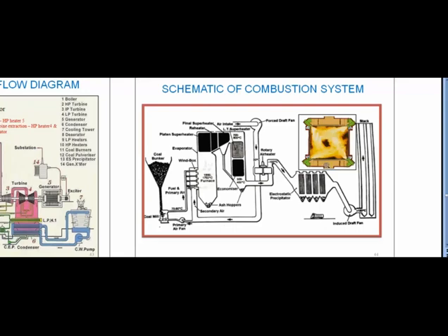Here also you can see the 4 corners in this corner fired furnace, and the coal and air is supplied from all the 4 corners. Some of the ash, which amounts nearly 20%, bind together to form lumps which fall into ash pit at the bottom of the furnace. From here, these lumps are being crushed and mixed with water, and this slurry is finally sent to the ash pond.